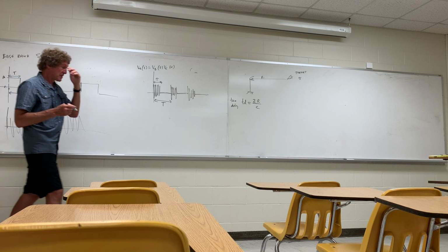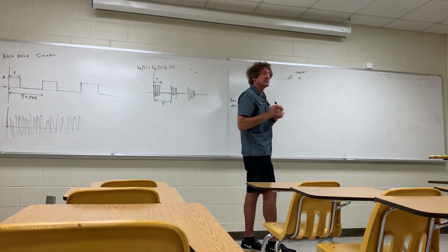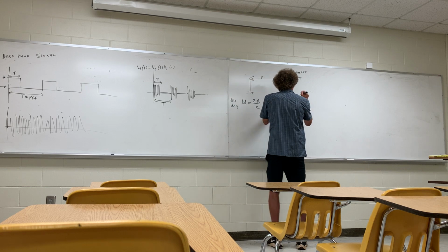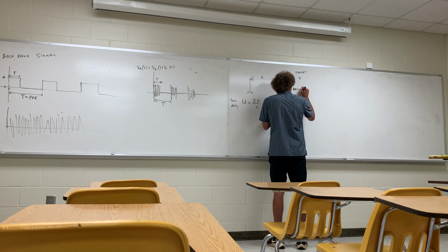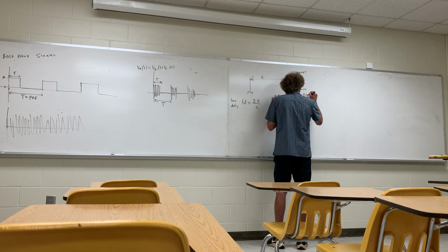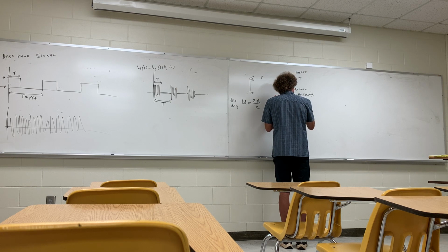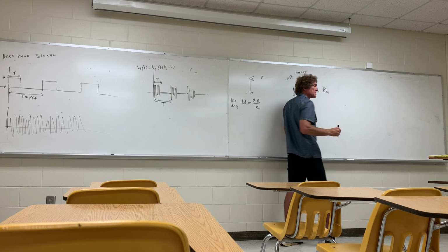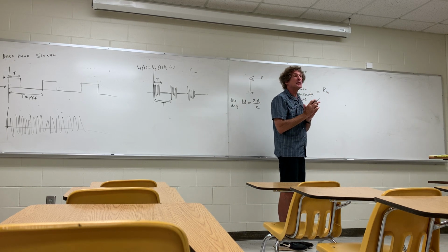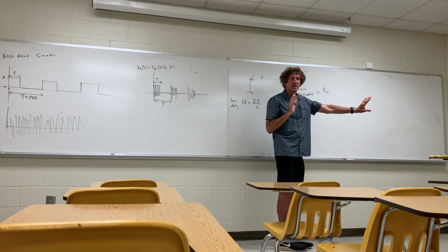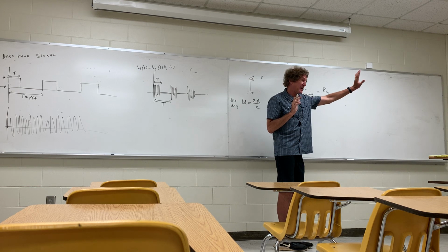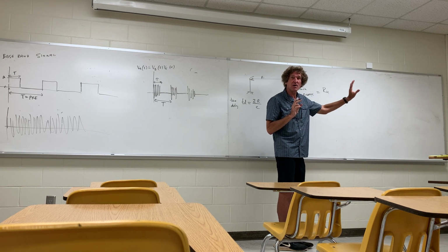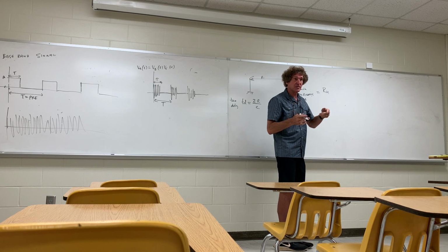So there's a thing called the maximum unambiguous range. Can I write this down here? Unambiguous range. It's really R sub U, the symbol used in the radar world all the time. It means this is how far we can see and not worry about the target being ambiguous. From that range inward, we're fine. If it's beyond that, and we get an echo return, it's ambiguous, but I'll tell you more about this.